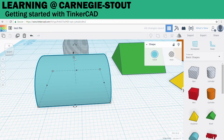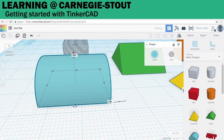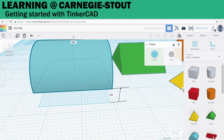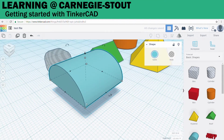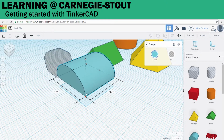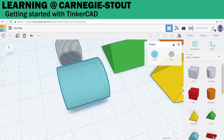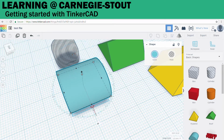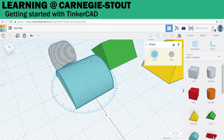You will also notice a white dot up top, as well as a caret. The white dot will change your item's height, and the caret will change its position relative to the work plane. Now, if you hold Shift while you click on a dot and change it, it will change the shape uniformly. In addition to the XYZ controls, you will also see 3 angle adjusters. You can click on any one of these and drag it around to change the angle of your object.